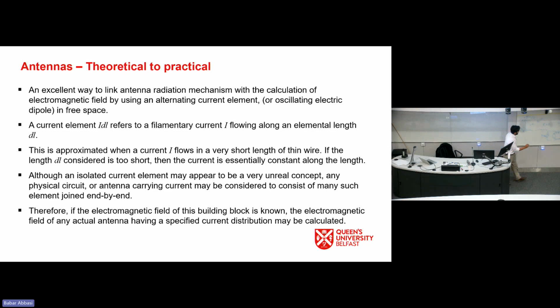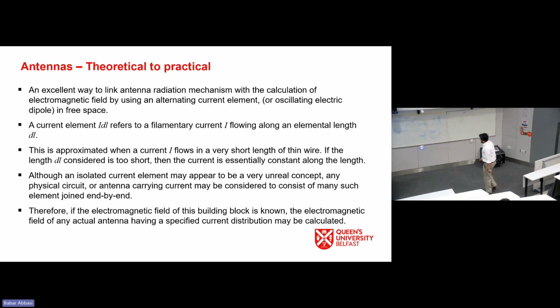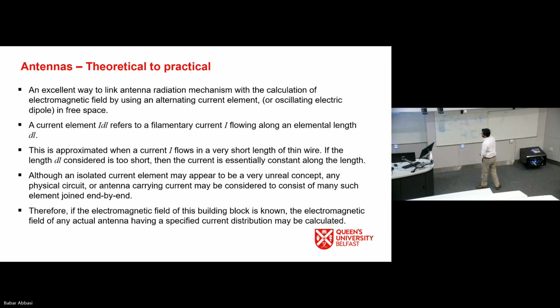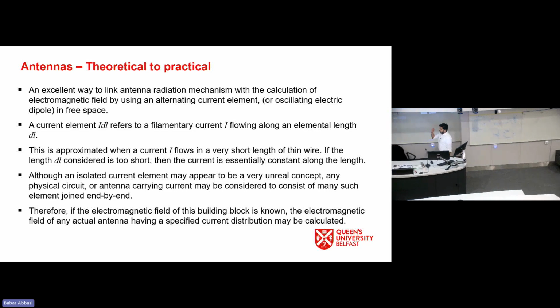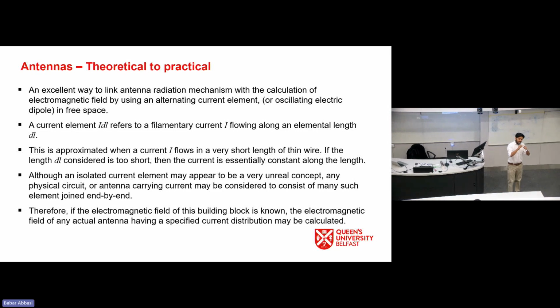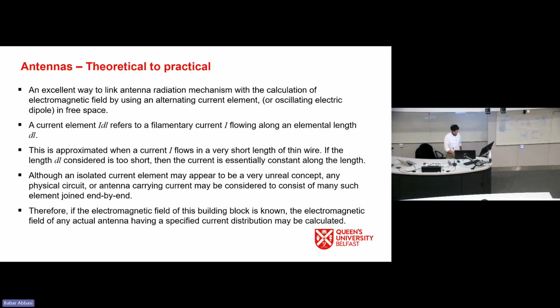So the simplest form of antenna is basically this phenomenon happening at a small strip level. What happens is we will have a small positive charge, and with it a negative charge. And we flip this positive and negative charge like this at a given frequency f. Because of this frequency f, there will be radiation happening. This is the simplest form. Some people call it a Hertzian dipole. I call it a simple dipole.